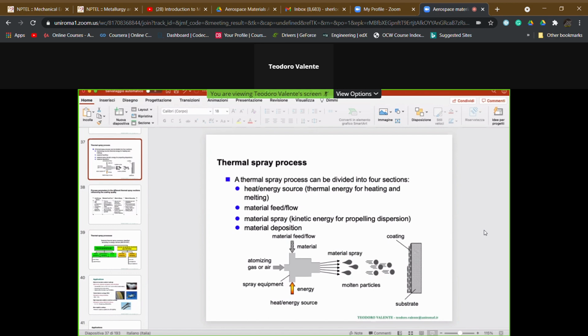And we have already seen, as will be clear in the next discussions, that the most important techniques for us, at least for our application, not for all, are high velocity oxygen fuel for the thermal spray by gas, and plasma spraying for thermal spraying where an electrical gas discharge exists in order to have the heat generation.